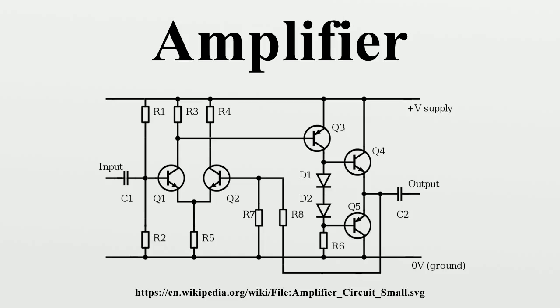Transistor-based amplifiers can be realized using various configurations. For example, with the bipolar junction transistor we can realize common base, common collector or common emitter amplifiers. Using a MOSFET we can realize common gate, common source or common drain amplifiers. Each configuration has different characteristics.